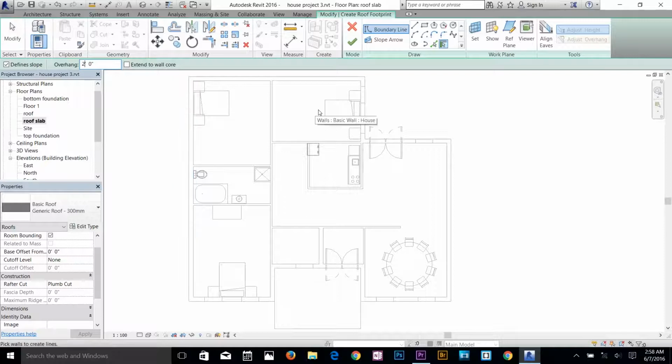Okay, alright, so you can basically draw a roof by using these tools, but what I recommend is picking wall is better. So select that pick wall option and just click. Let's say if you move your cursor to the right, it's going to draw a roof on the right. It's just spacebar or tab.